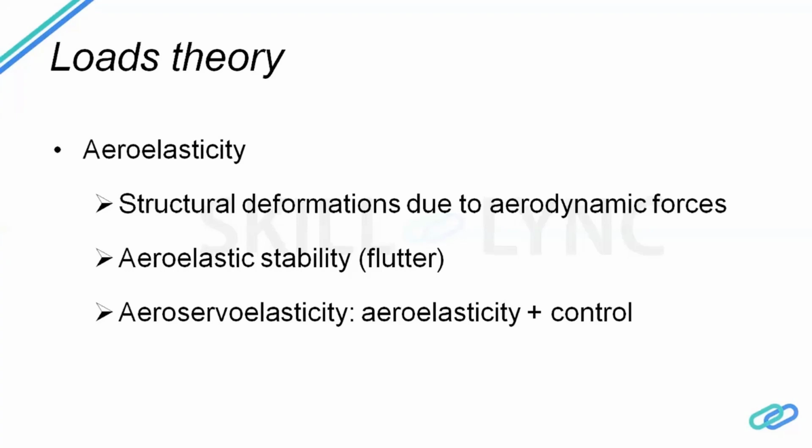The bridge fell down due to excessive flutter. Sometimes this event is referred to as resonance, but that is not true. What happened to the Tacoma Bridge was flutter. You can see that the bridge oscillates up and down, and there are also lateral oscillations. It was the wind that led to the flutter event.